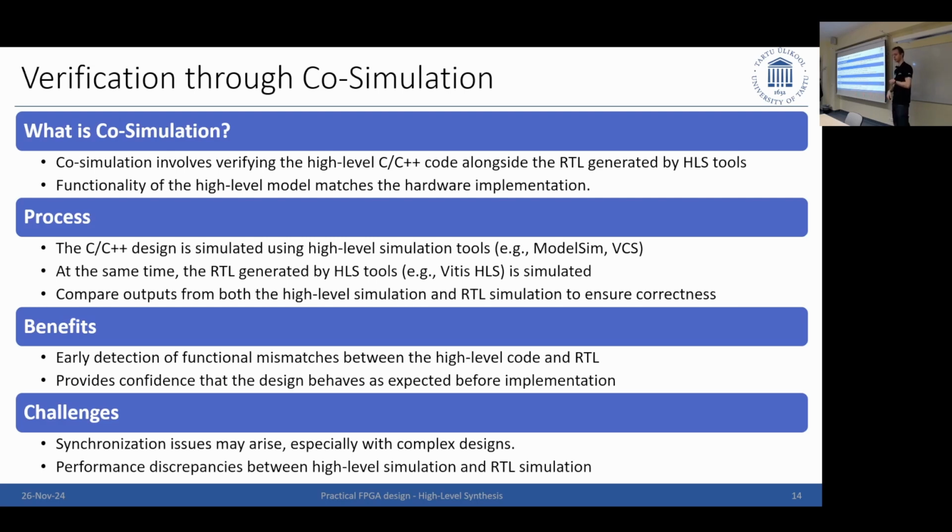For what other people do in the process, it will only be useful as soon as you have your algorithm already implemented in VHDL. Otherwise, my output is obviously going to be different from the Python or MATLAB simulation output I have. So this is mostly used for verification, or when I've designed changes and I want to make sure that this still is correct and behaves as it should.